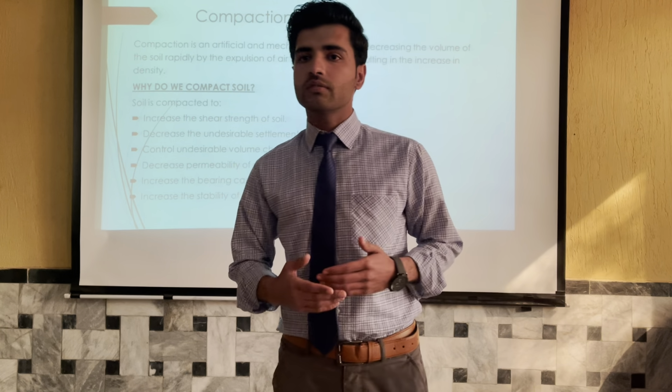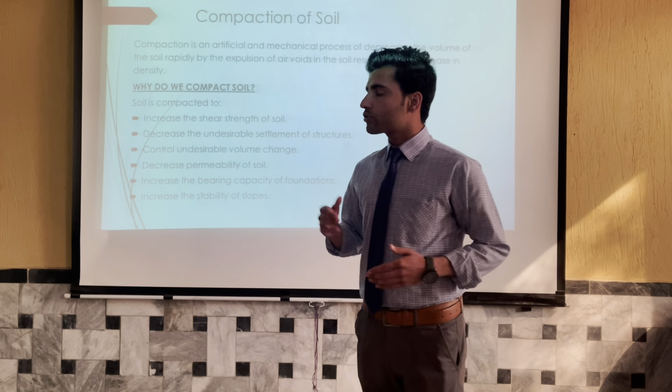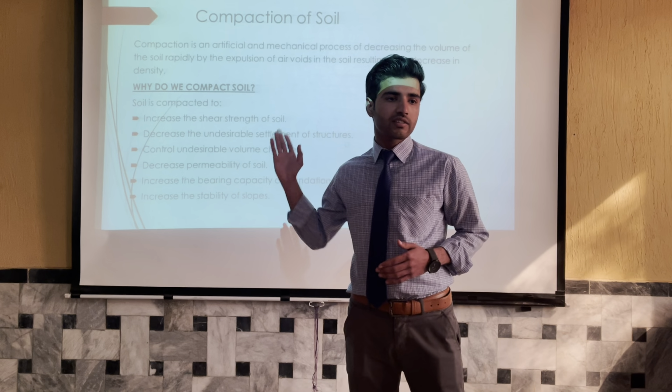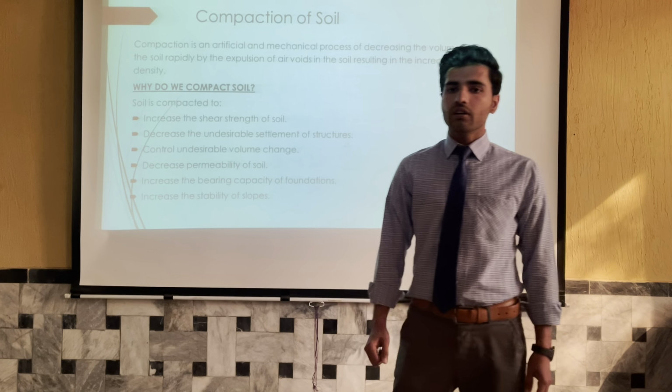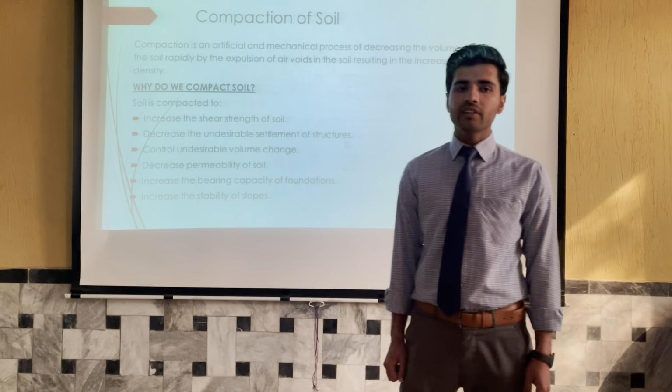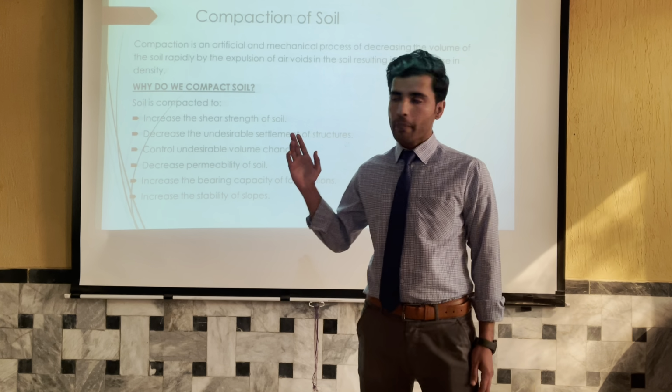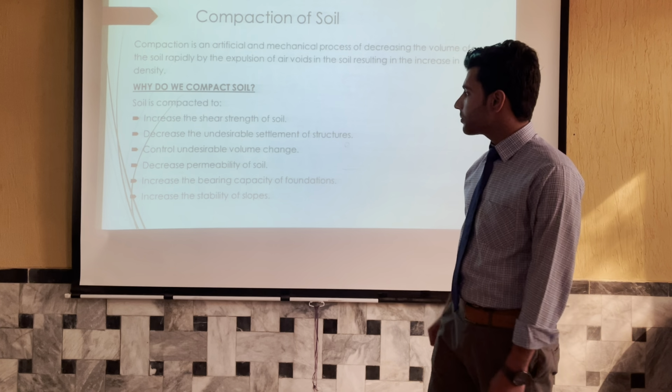There are a few reasons for which we do compaction. The first one is to increase the shear strength of the soil. The second one is to increase the slope stability. The third one is to decrease the permeability of the soil.